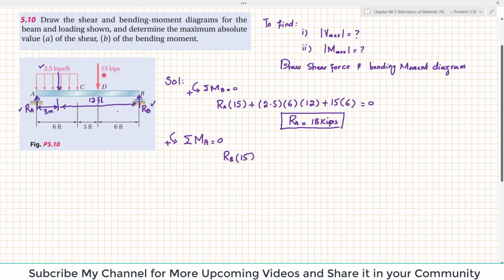The second force producing moment about point A is 15 kips. So 15 times the perpendicular distance of 9, and since this is producing clockwise moment, it will be negative. The third force producing moment is this distributed load. Again, this load has to be converted into a concentrated load.